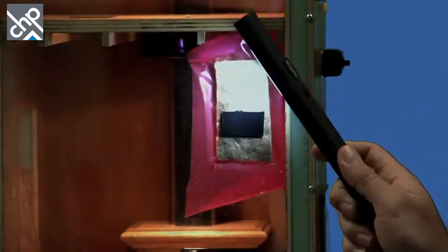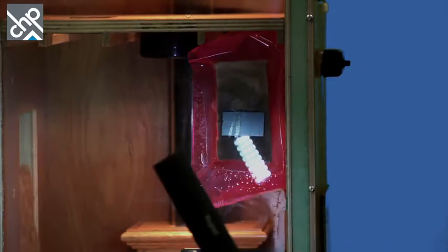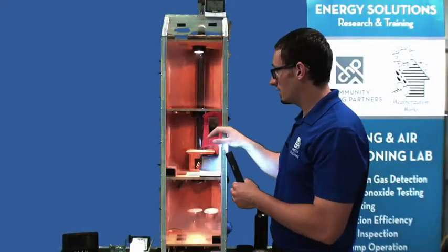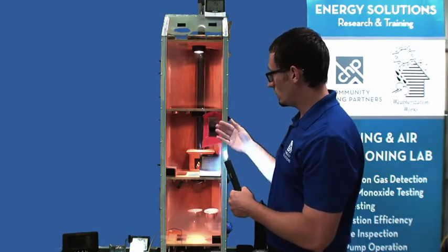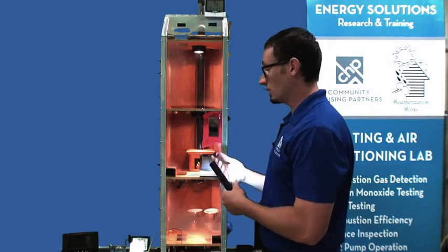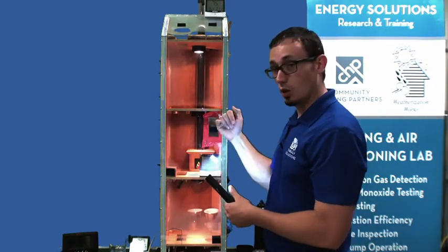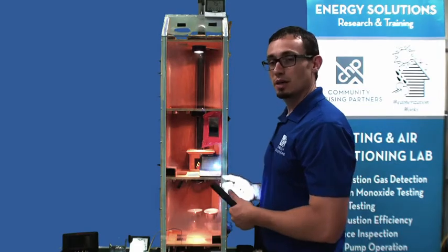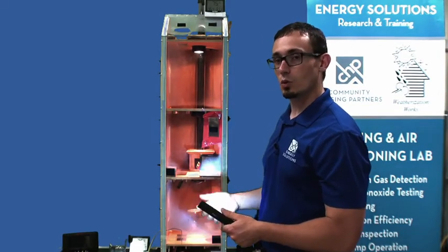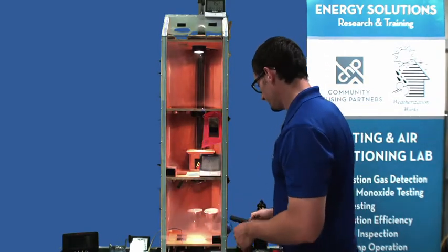Nothing. Why is that? That's because we've got a proper air barrier that's going to prevent that moisture-laden air from trying to get through this wall to hit this cold surface, because that's where the air wants to go. It's hot and it's moist. It wants to go to that cold surface, but it can't because we've got an air barrier. We controlled that air movement. Okay.